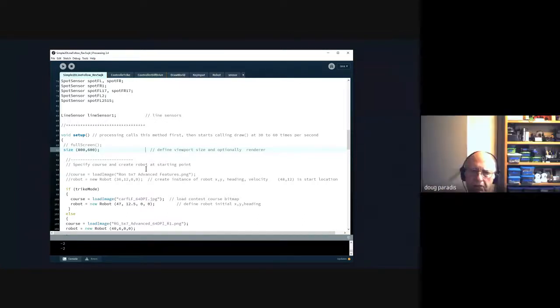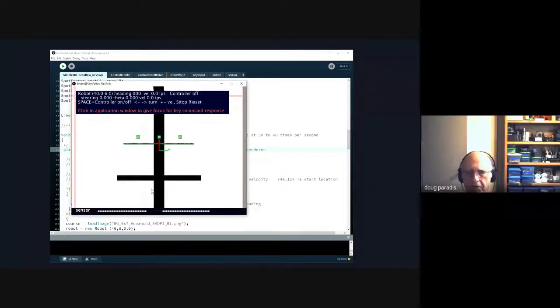I guess what I'm thinking is probably where you place your sensors then with respect to your center point in the wheelbase, because obviously if you have a big robot like a 15-inch robot, and you're trying to turn on a 6-inch radius, you would have to turn one wheel forward and one wheel backwards.